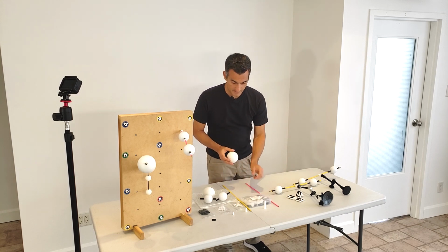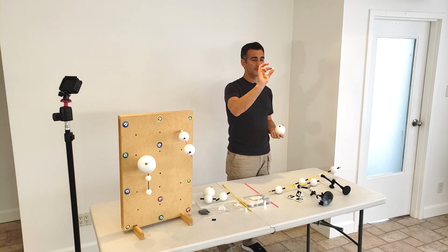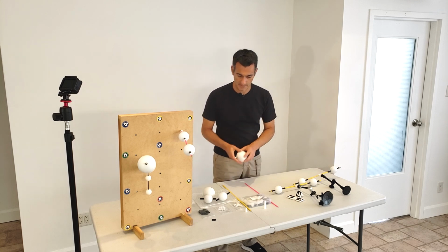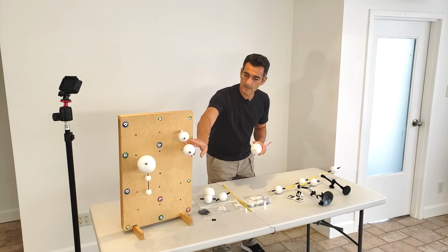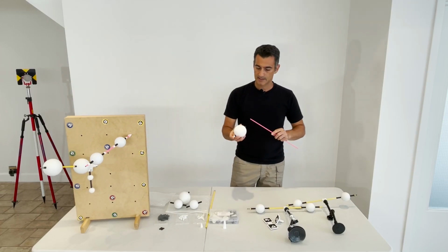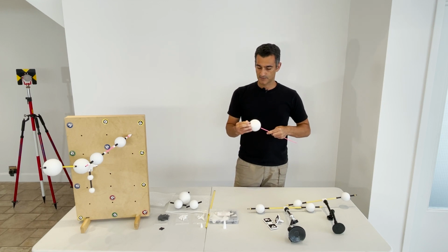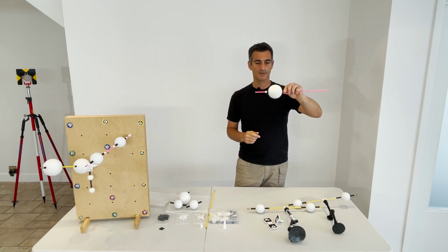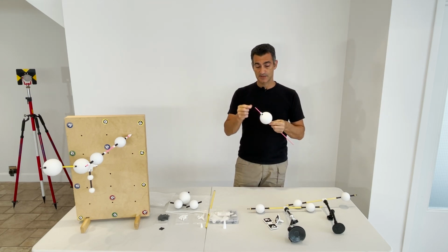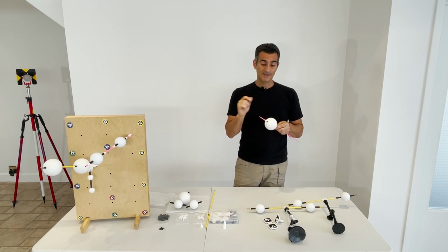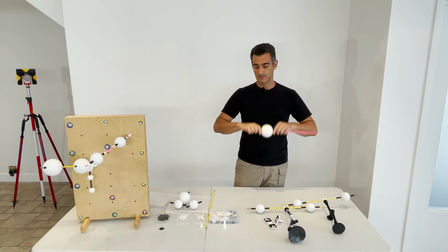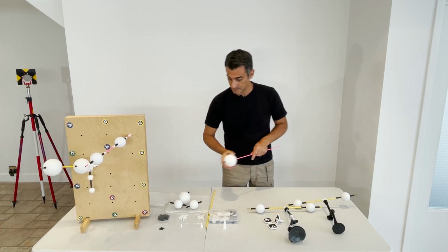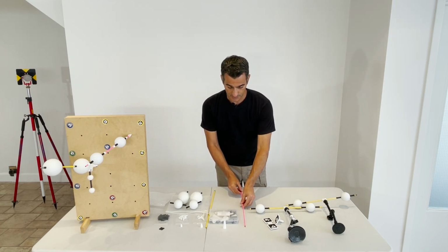For that, what we have, and I've 3D printed these, are these little adapters. They just go on the end, and they're really just reducers. I'll put one on here, but over here I actually have two of them. When you put the rod through, it adapts to the smaller size. I only have it on one end, but I would put it on both, and then it doesn't rattle around. That's important. If you're using the smaller rod and you've got the 1/4 inch hole, you can't put this on directly. You need some kind of reducer to hold it in place. These are just parts that I've 3D printed, but maybe there's a place that sells them. I'm not exactly sure.